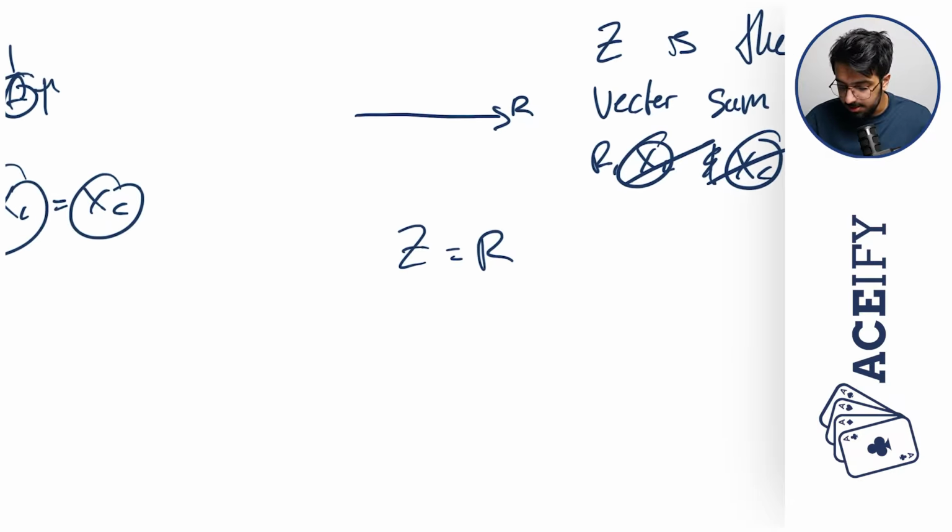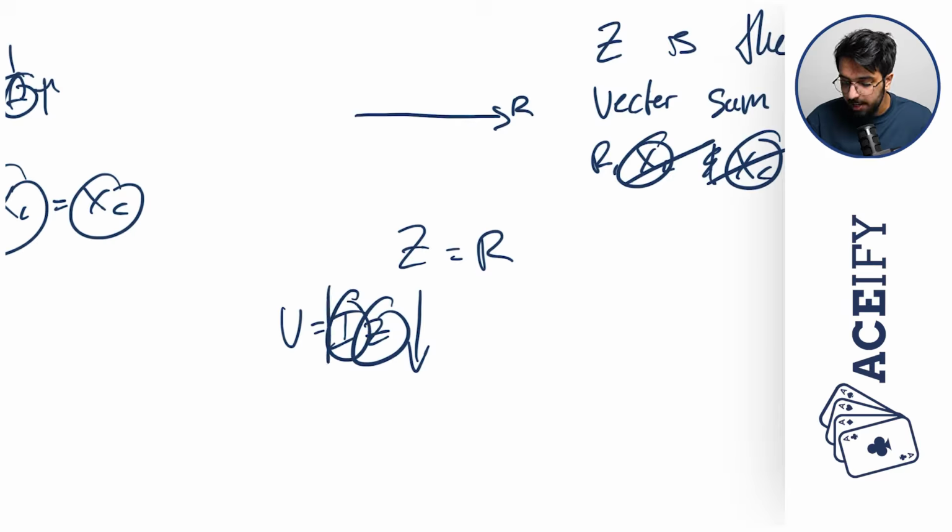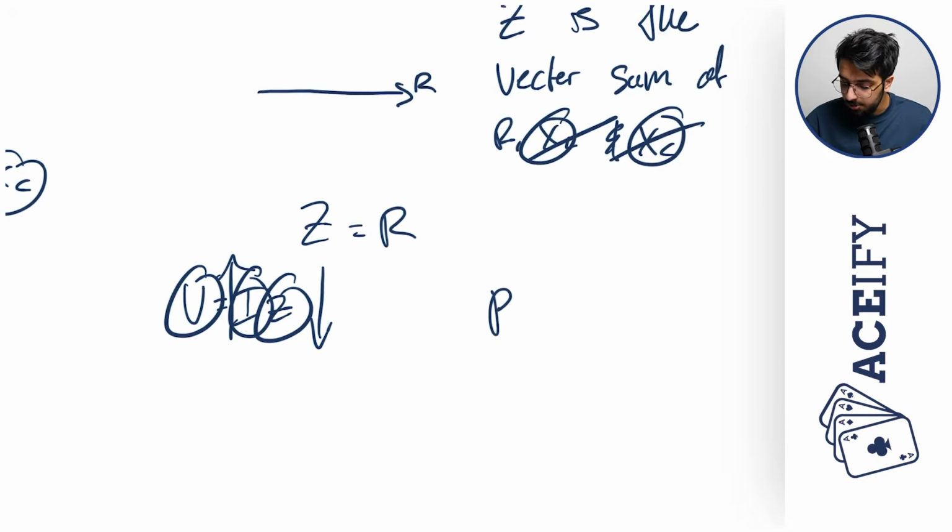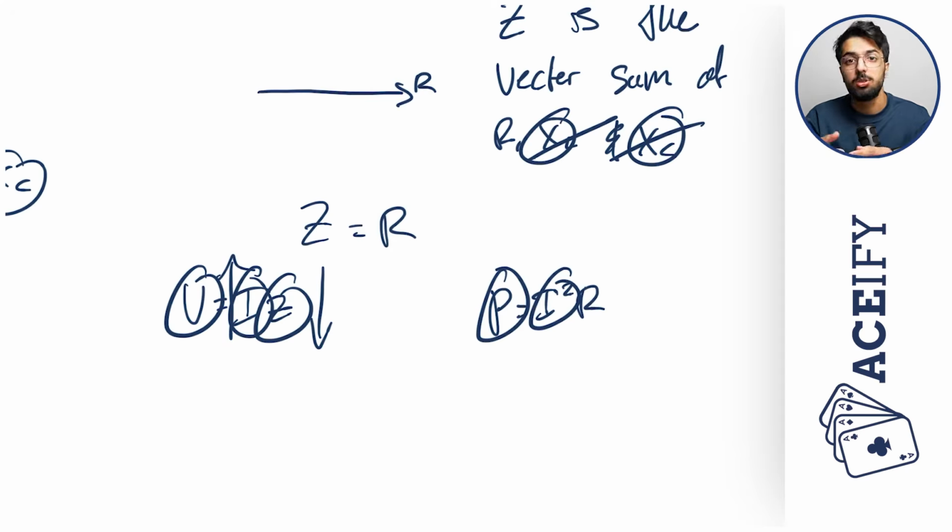And because V is equal to IZ, if our impedance is at a minimum, therefore our current is going to be at a maximum because our voltage has remained the same. And because P is equal to I squared R, if our current is at a max, the power used by the bulb is going to be a max, and so it's going to glow the brightest.